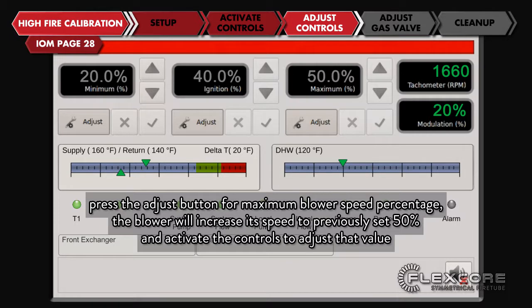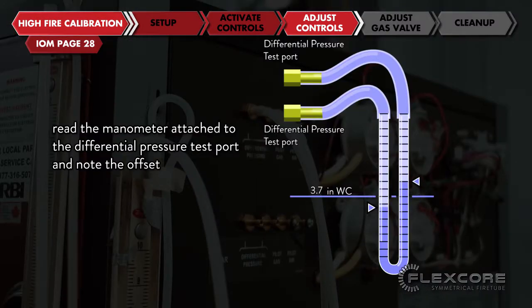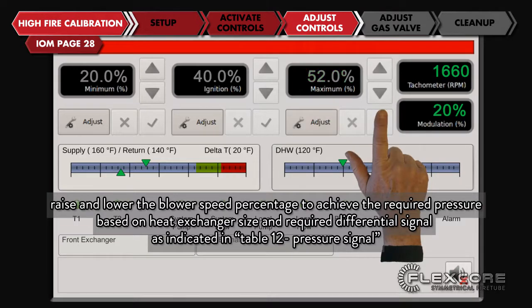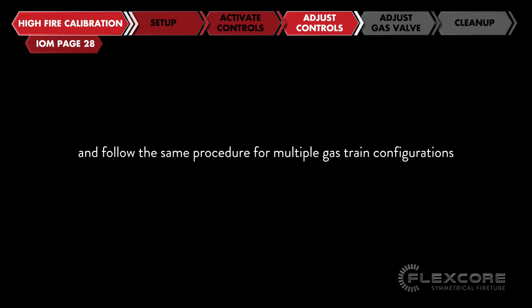Press the adjust button for maximum blower speed percentage. The blower will increase its speed to the previously set 50% and activate the controls to adjust that value. Read the manometer attached to the differential pressure test port and note the offset. Raise and lower the blower speed percentage to achieve the required pressure based on heat exchanger size and required differential signal as indicated in Table 12, Pressure Signal. And follow the same procedure for multiple gas train configurations.